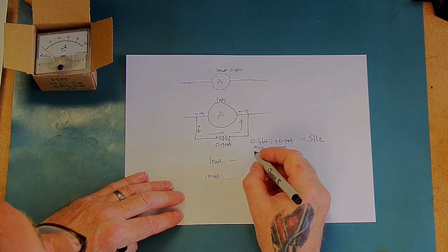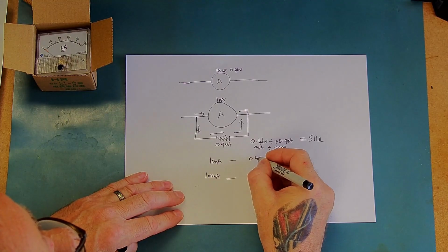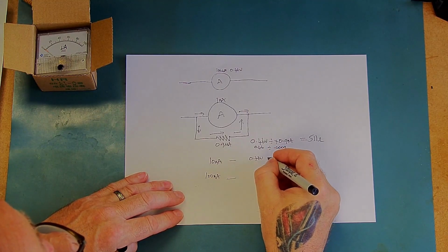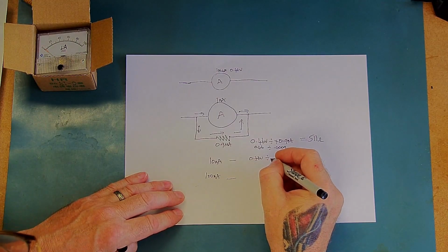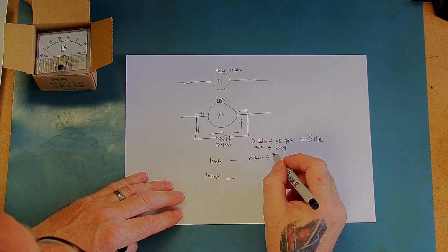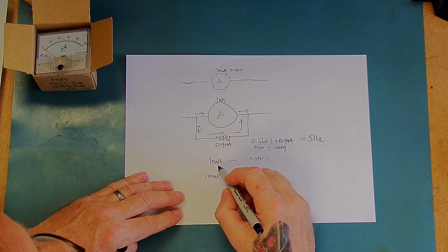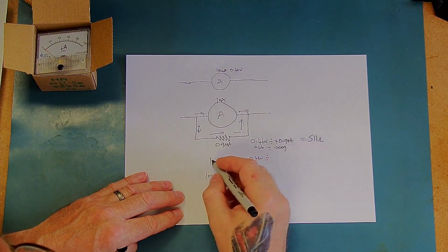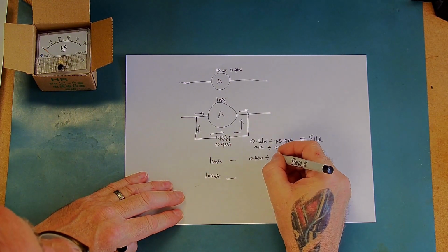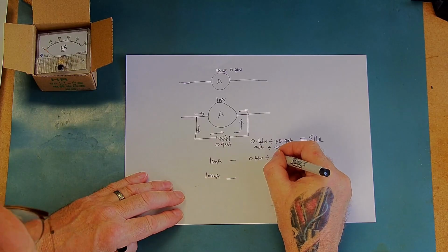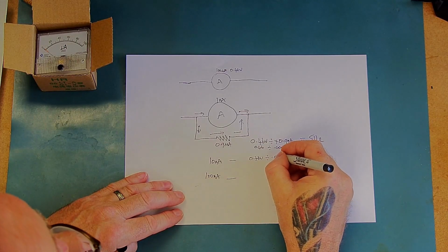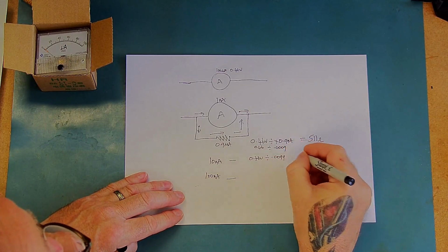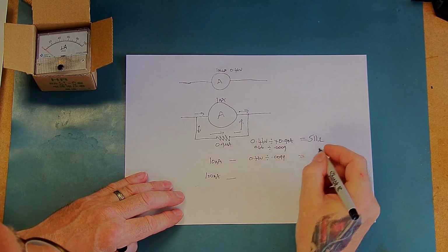So we need 0.46 volts because that's full scale deflection, and then we divide that, assuming in the 10 milliamp range we will have 9.9 milliamps passing through the resistor. So we divide that by 0.0099, and that will give us the next one.